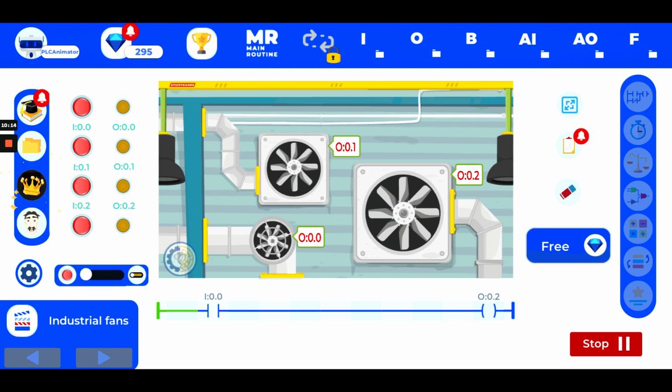Now, where is it allowing it to? To our PLC input. So then it is respecting our program, because it's saying as long as you allow my voltage flow or my signal to go through, you are going to stay on. And this is staying on actually. Now, at a programming level, what did we do? There is a part below our push buttons where we can select between one input type and another. The first type is push button.